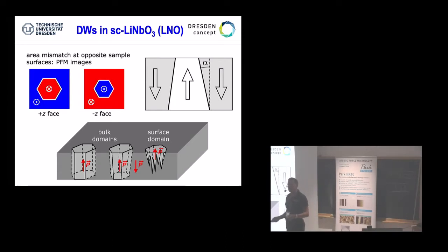So from that point of view, we are clear about this material, lithium niobate, grown like this, and I will break the ice for this, because this is something that industry likes. This lithium niobate is a wide bandgap material, with a gap of 4 electron volts. You can dope it if you want. We don't want to do it here. But what is even more intriguing is that it's fully CMOS compatible. So industry likes it because you can do everything integrated on a chip level.